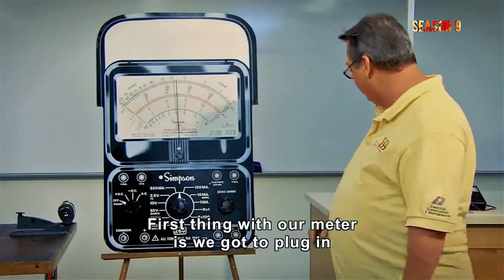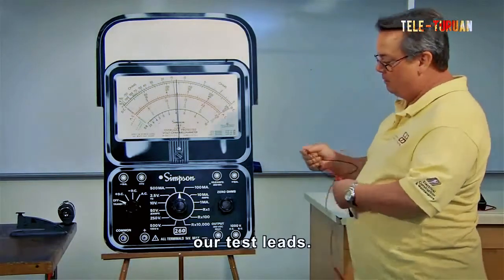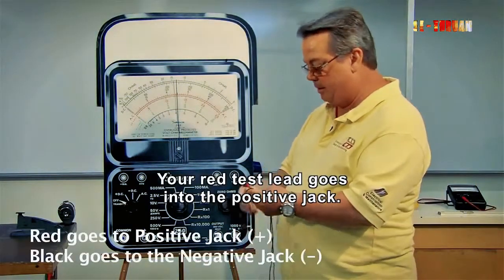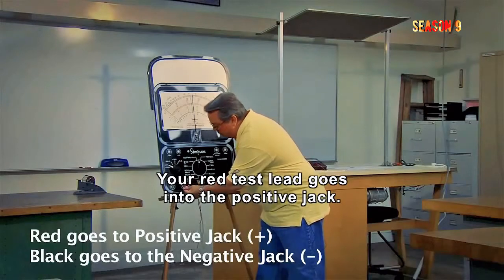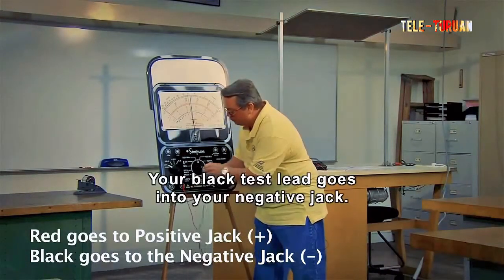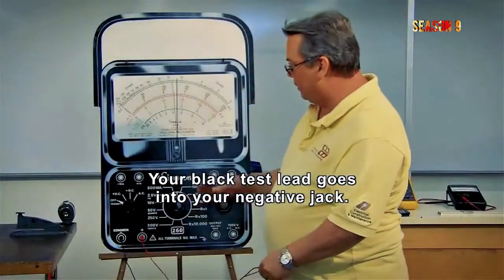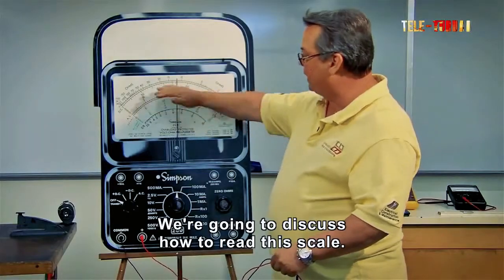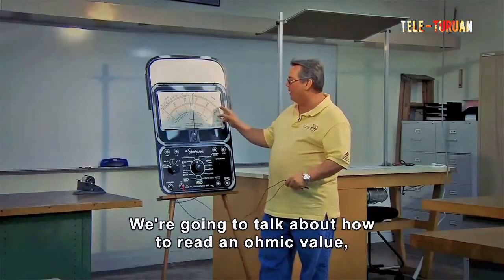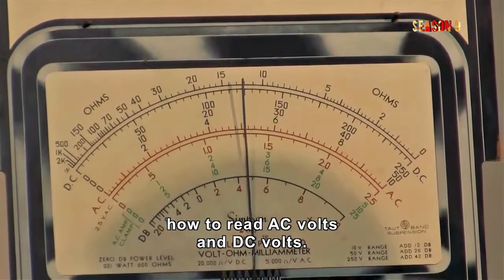First thing with our meter is we got to plug in our test leads. Your red test lead goes into the positive jack, and your black test lead goes into your negative jack. We're going to discuss how to read this scale. We're going to talk about how to read an ohmic value, how to read AC volts, and DC volts.